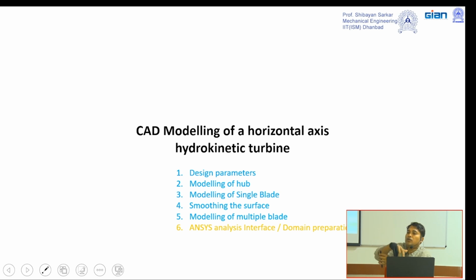In our laboratory also we have tested a vertical axis turbine, but after a few days, a few months, we saw that instead of behaving vertically, it had actually been tilted. Now whenever it is tilted, the force which is striking the blade will not be uniform. The force striking the lower part of the blade and the force striking the upper part of the same blade will be of different magnitude. Then it is creating problems.